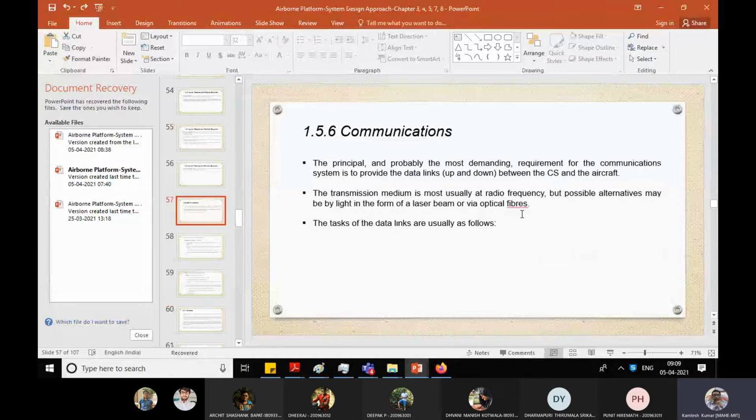Okay, so the pilot will take off the aircraft. For taking off, they will give all the commands to the GCS, not like your transmitter giving directly to the aircraft. So the transmitter data will be transferred through the cable to the GCS, and then the GCS will upload the data through the antenna to the aircraft. Okay, so you have to get that idea.